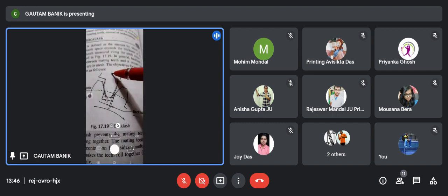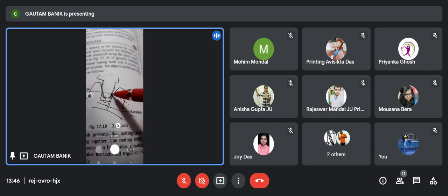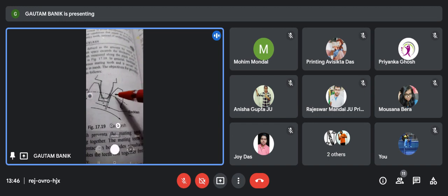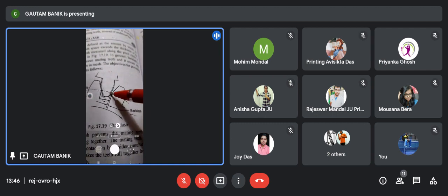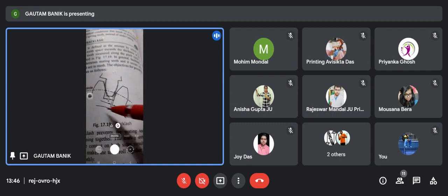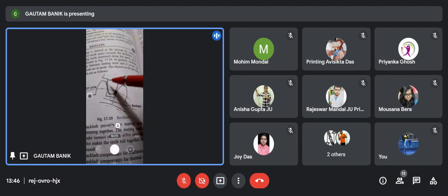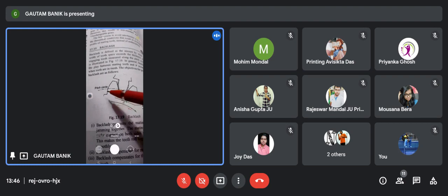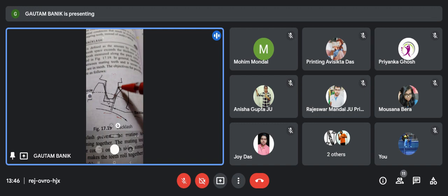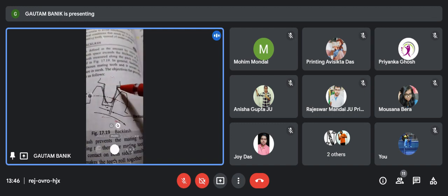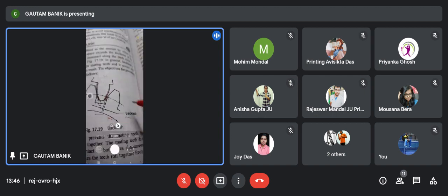When this is the pinion and it rotates, it has to cover this distance for transferring the power. Until this backlash is covered, the follower will not rotate. So this is geometrically showing the backlash. It is called backlash because at the time of rotation, due to wearing and corrosion, the size of the gear teeth is reduced.